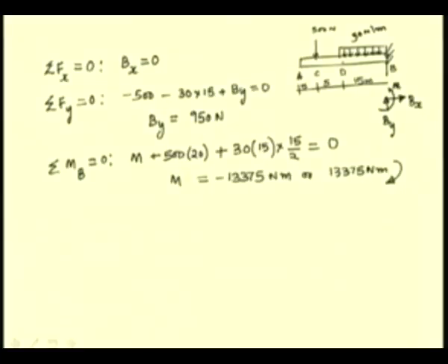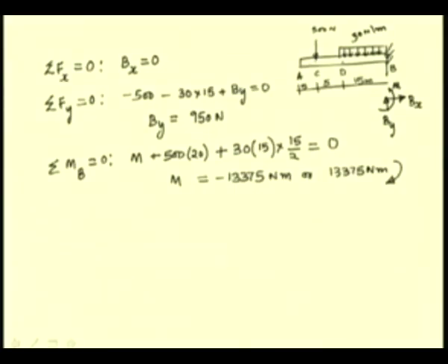In order to construct the shear force and bending moment diagrams, we can take sections for which the loading patterns are similar, because the behavior of the shear force and bending moment curves will be constant or same for a portion where there is no change in the loading behavior.